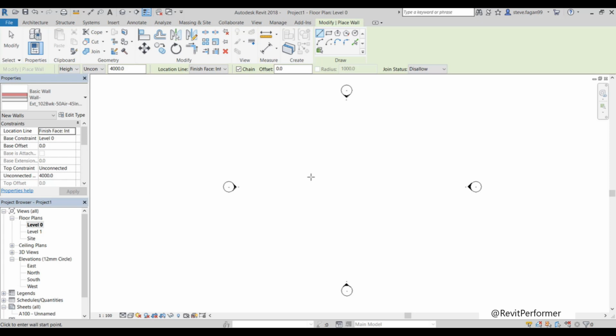When we're modeling a project, we are presented with multiple modeling aids. These aids will appear on almost all of the components which we will use. So if I draw my first wall and draw another wall above it, first thing we'll get is our temporary vertical dimension. So you'll see that there's a dashed blue line. That is telling me that that wall, when I start it, will be snapped directly above it. I can also use the temporary dimension to specify the distance before I've even started.